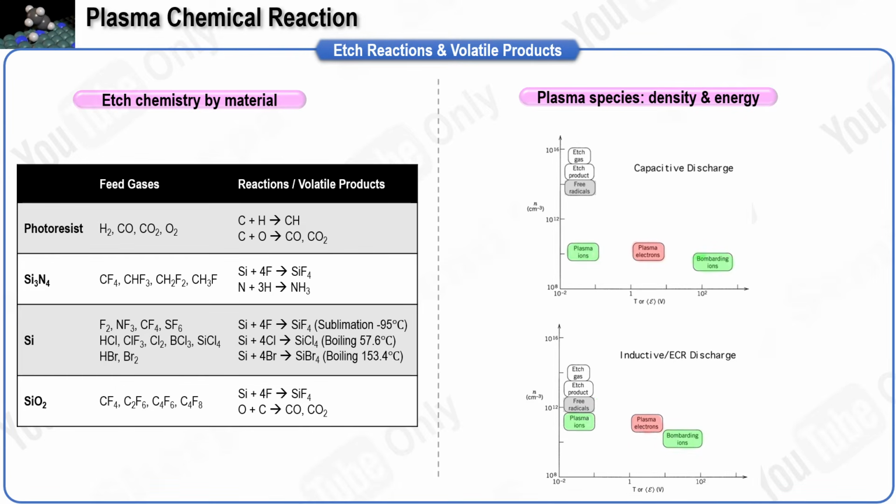When the plasma is on, many plasma species appear. There are neutral feed molecules, dissociated radicals, positive ions, and electrons. The etch characteristics depend on the density of these species and the energy they carry. The feed gas itself has the highest concentration, but it is far less reactive on the wafer than radicals that come from dissociation. Radicals drive the chemistry that forms the volatile products. Ions accelerated through the sheath strike the surface nearly normal to the wafer and add directionality and synergy.